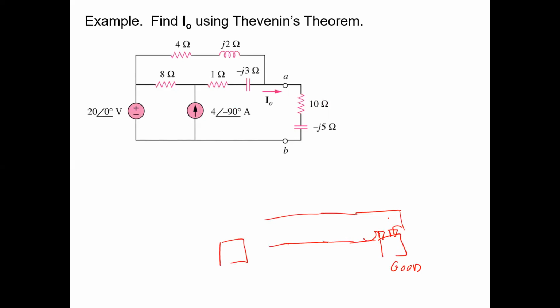If this is the plus side, you connect the plus side to the bad battery's plus terminal, but you connect the minus side to the frame of the car. You can connect it to the engine block, your valve covers, somewhere where there's a big, good metal connection.